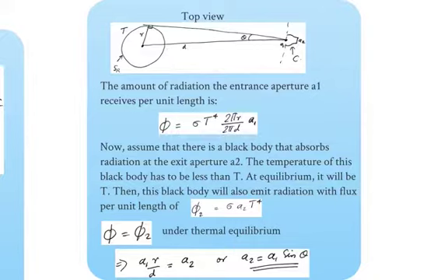And phi is the radiation which is entering the CPC. Now, these two things have to be equal at equilibrium. Otherwise, the temperature is changing. Right? When we say equilibrium, the temperature is stabilized. So they have to be equal. So whatever is coming in here must be equal to whatever is leaving. So phi should be equal to phi2 under thermal equilibrium.